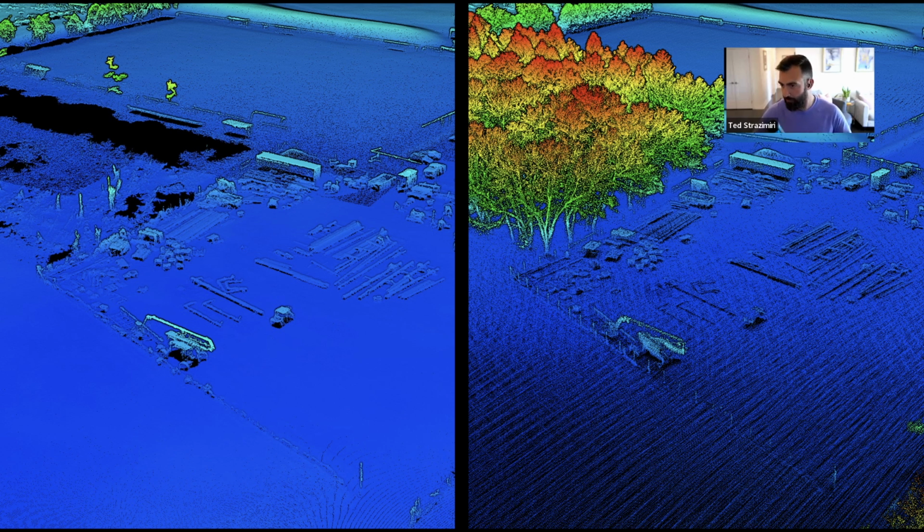Terrestrial laser scanning is going to be more accurate, by almost an order of magnitude, more precise as well, just because it's on the ground. It's generally a much larger payload and much larger sensor. And it's also not moving in a lot of cases. But the efficiency is borderline horrible, right? You're not using that for its efficiency, you're using it for its accuracy and precision.